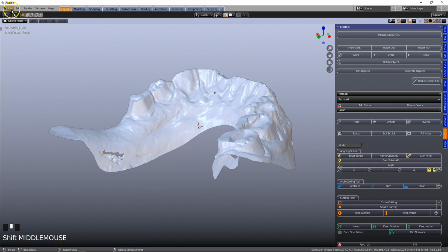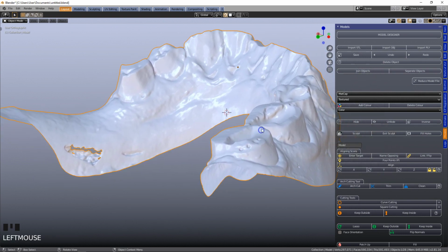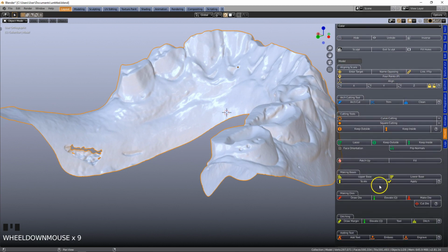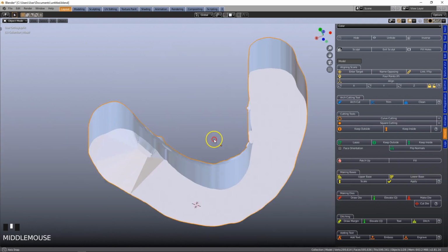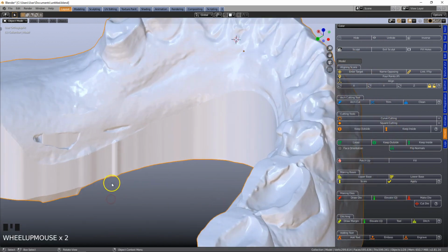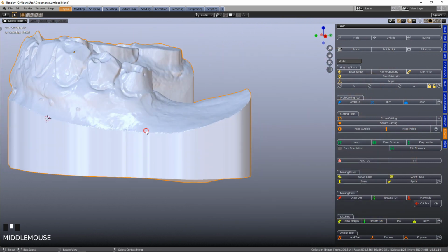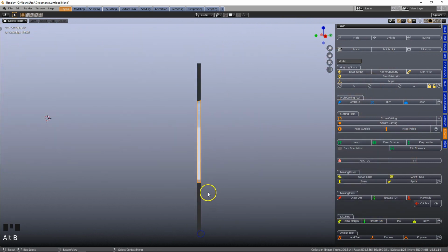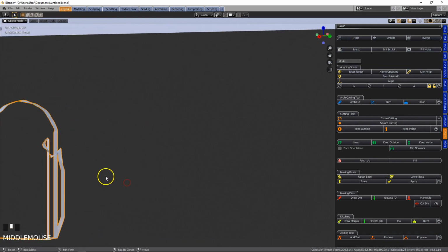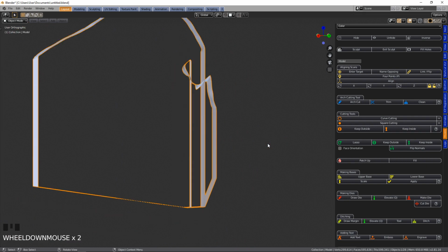I'm just going to save this. Always save your work. So if hypothetically we extrude this, look what happens. Lower base, it mucks it up. It takes the holes, and on the inside it won't do a good job. If we cross section it and I view it on the inside, it's not a good mesh, and you may have problems printing this.